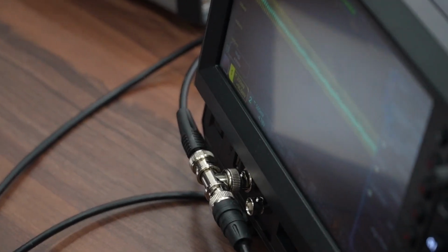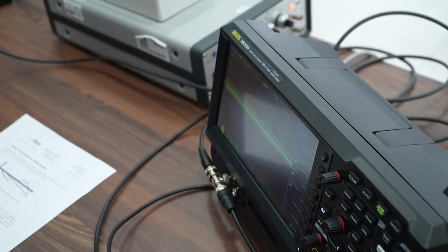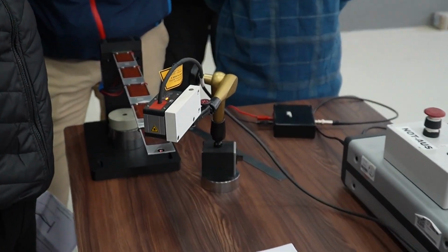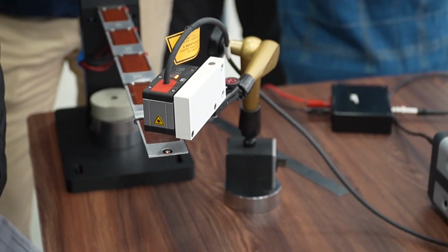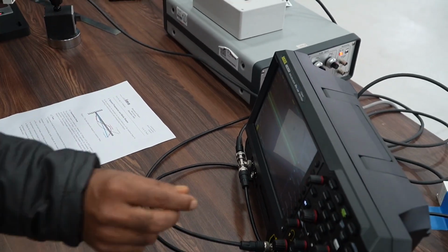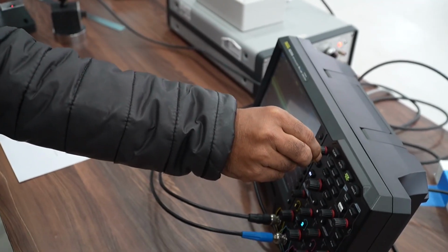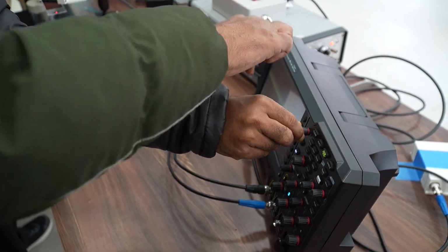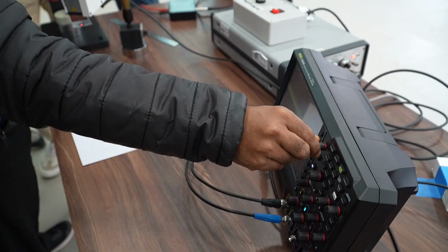How much? Stop and check. Just look at it. One quarter. T by 4. So 360 by 4? So the 180 by 4. What is that? That's the phase shift. 45 degree, perfect. If you're in the eigenfrequency, you will exactly see a phase delay of 45 degrees.